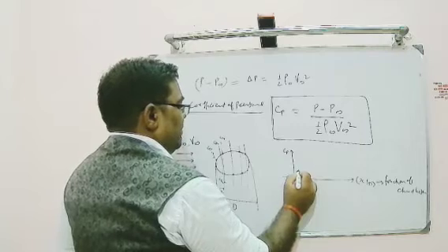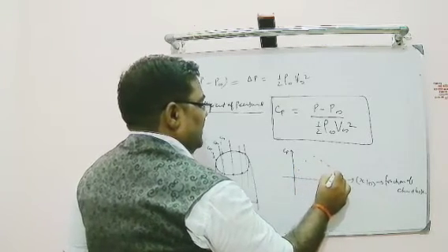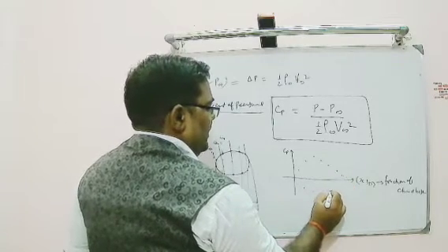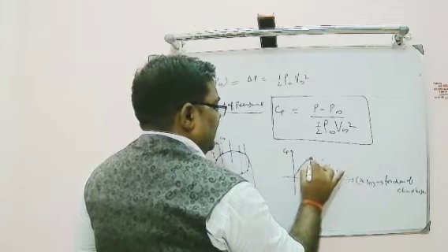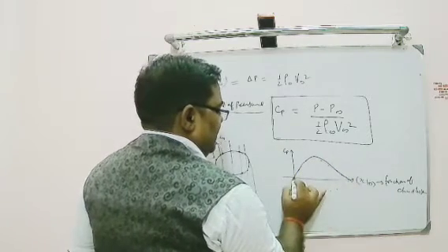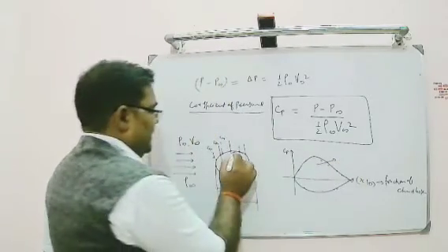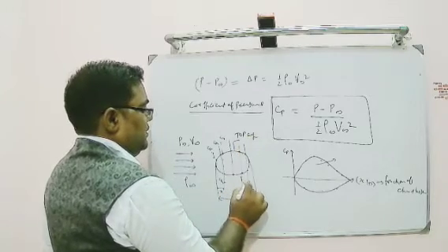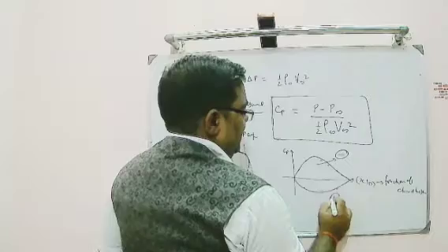So Cp1, let's suppose one point is coming here, another is coming here, it is going like this, now going like this, whatever points. Similarly downside also. Now I can connect point by point in this way, and I can get this curve. This is the top surface, and this is the bottom surface. On the top surface this is negative pressure, here positive pressure.